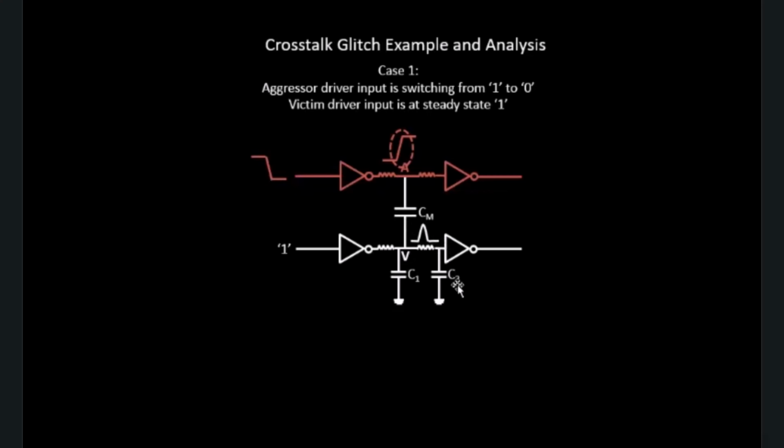So there are two things to observe over here. The first thing is whether this particular glitch, as it is basically called, is a harmful glitch, or how it affects things. We learned in the previous video that if this voltage lies below 100 millivolts in a 0.1 micron and below process, it will be considered logic 0.